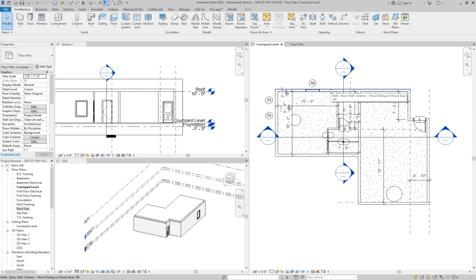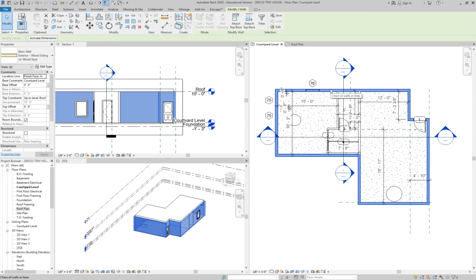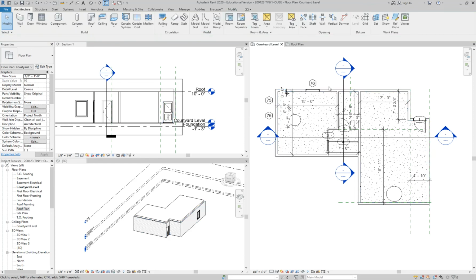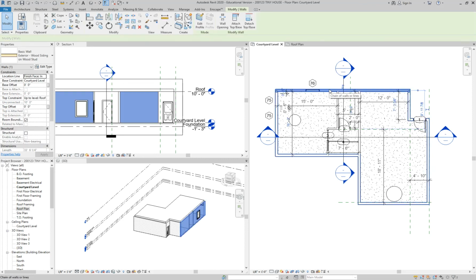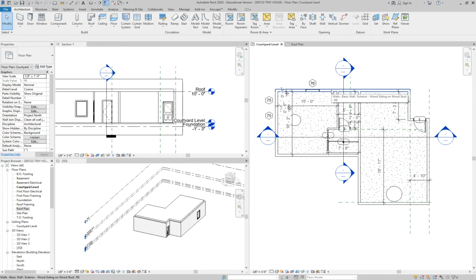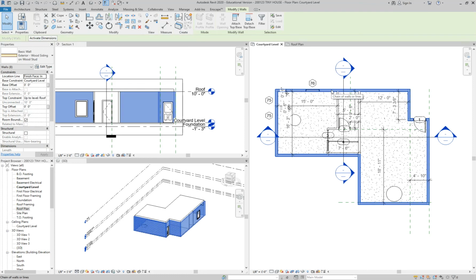So I'm going to hover, tab once and let go. See how they're highlighted? Now you click and they're selected. What I see happening a lot today is people are hovering, holding the tab key down, see how it's freaking out disco style, and then trying to click somewhere in here. Okay, so it's really just hover, tab once, I've let go, they're still highlighted, and then I click and now they're selected.